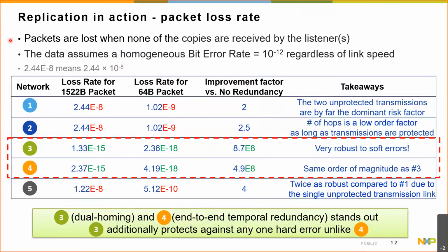Practically, to obtain those reliability values, we modeled the different replication scenarios with the RTaW-Pegase tool and then developed a Java plugin to the tool that implements a dedicated mathematical reliability analysis. And that's because injecting faults during simulation is not practical with the BERs of automotive PHYs, simply because the CRC errors are just too rare.